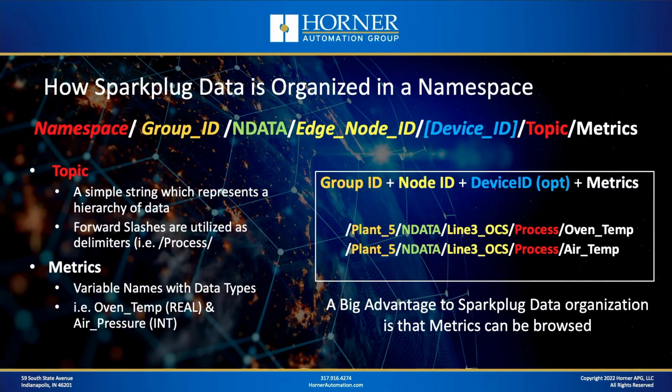Now, one of the big advantages of the Sparkplug specification, the way it's defined, is that it really is conducive for host devices. Remember, a host device is playing the role of a traditional SCADA package, but it's very conducive for host devices to be able to browse metrics or browse tags. So in a Sparkplug system, it's extremely unusual for you to have to manually type any kind of tag name or metric name into any host software package, because with Sparkplug, all that data is available to be browsed typically. So that's a huge advantage.